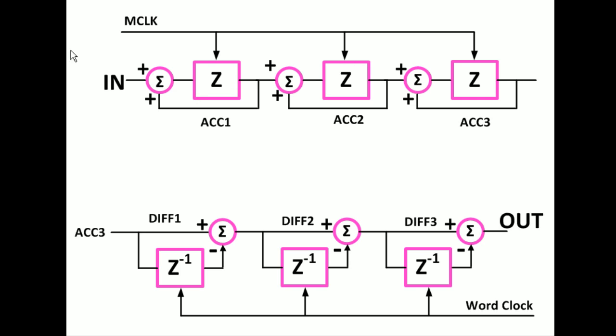So this is an averaging filter, a moving averaging filter, where the output coming out of here is the average of going through all these steps of summing with itself and ending up with a number that has noise filtered out of it also, because of the way summing works and integrating. Coming out of our integrating accumulation process, now we go to the decimator. So this drops down to here, and now we see in the summation that it's starting to subtract it out.